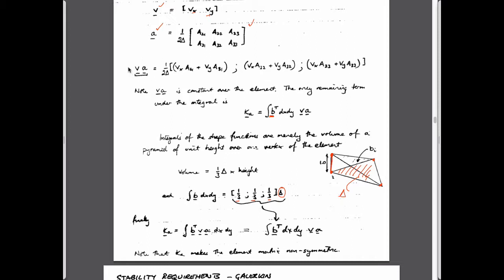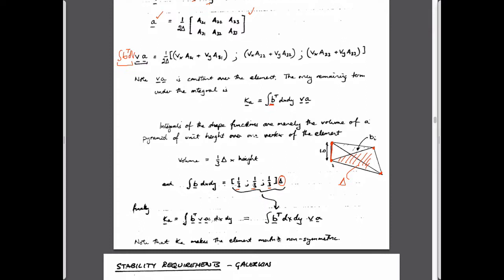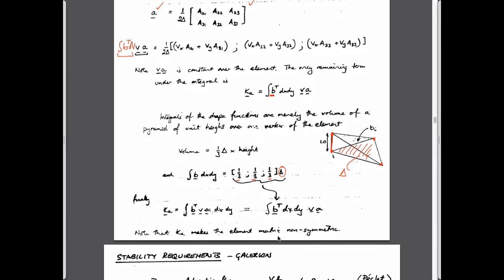And so now if we want to multiply by this component here, we just have to multiply this matrix by it. And so it becomes relatively straightforward to just multiply this matrix by the values of a third, a third, a third, and we end up with a 3 by 3 matrix which accommodates all of these components. So no more than that. And so we don't have to figure out what the shape functions are, just by thinking in terms of what we know about the properties of these individual component matrices.